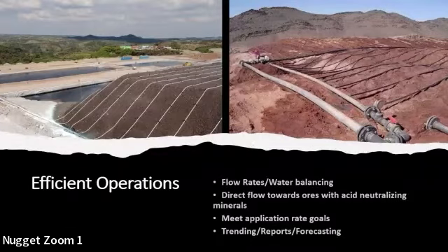So the consolidation permeability testing, just to go into a little bit more detail about what that test is. It's a dual wall, flexible wall cell that's packed, typically we use a 6-inch or 12-inch diameter cell that's 12 inches long. It really depends on the particle size distribution, how coarse the particles are, and the largest particle size. What we do is test at variable bulk densities, or variable consolidation. What that allows us to do is understand the saturated hydraulic conductivity of the ore under different heap heights or depth in the heap.